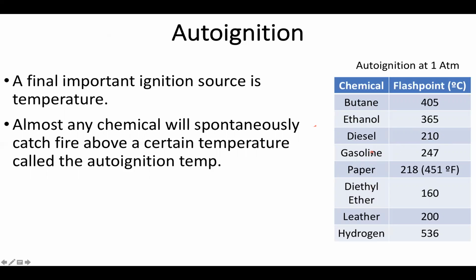So for example, diesel has a relatively low autoignition temperature, and this is more or less the idea of how a diesel engine works: I raise the pressure high enough so that the flash point decreases enough that I don't need a spark plug. However, when I'm dealing with something like gasoline, one of the reasons I use a spark plug is because the autoignition temperature is much higher.